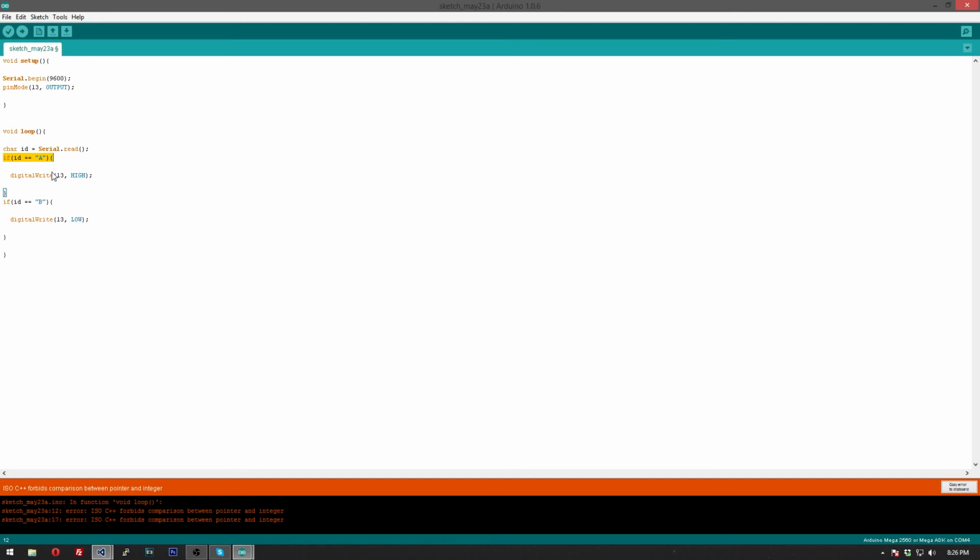Oop, what's going on? Aha. These ones represent a character, and this is a character. This represents a string. This is a character, not a string. So let's go ahead and fix that. I forgot Arduino's a little different. Let's upload that. Now we should upload without any errors, hopefully, maybe.